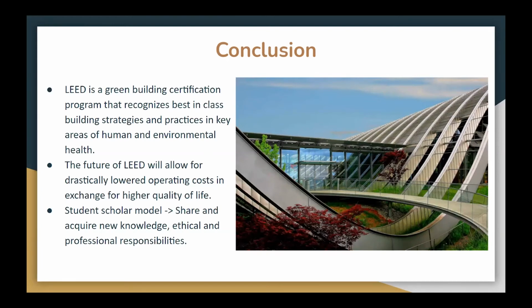Yeah, we did incorporate that in the code analysis. I mean the cost analysis, because we incorporated the cost for construction, which also includes various inspections, which are not only city inspections but also HERS raters and Title 24 raters. During construction, the HERS rater comes in and checks that we install the proper windows and the proper insulation throughout the building. They also check the HVAC system as well. Thanks. Thank you.